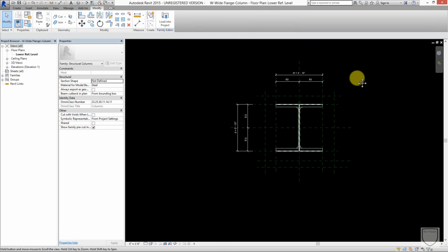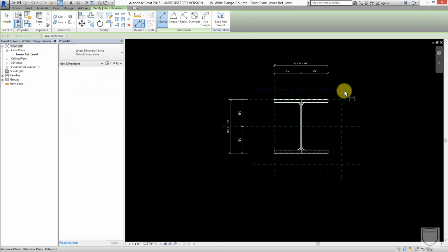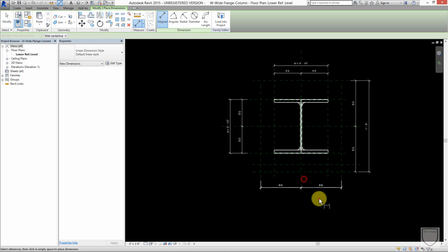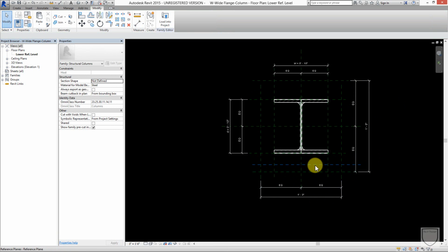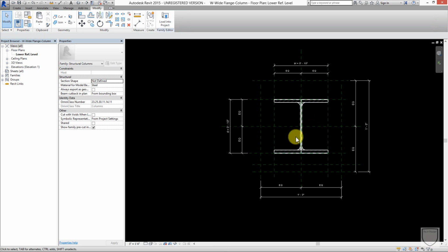I'm using these reference planes because I'm going to create an extrusion for an implied column enclosure. And I'm also going to make it parametric. So I'd like to put some dimension strings here to equal it out, and then a governing string, we'll call it. That allows me to equal it out, and that will allow me to control the width. In this case, you should also be aware that I set up these strings to maintain, which is soon going to be my enclosure around this column. Make sure that these particular dimension strings are pinned or it will deviate slightly. In this case, they're okay.